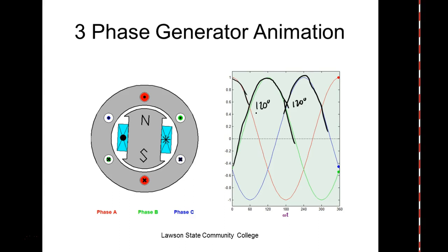Well, what happens is now I'm adding another conductor. So when we send 3-phase, we have to send it in at least 3 conductors. If I was to measure that current there and measure that voltage there, we know that power is equal to V times I. But the problem is we're spreading it over 3 wires. So the actual formula for 3-phase is V times I times the square root of 3. So basically, we add one more wire, but we carry times the square root of 3, or 1.73, more power on 3 wires.